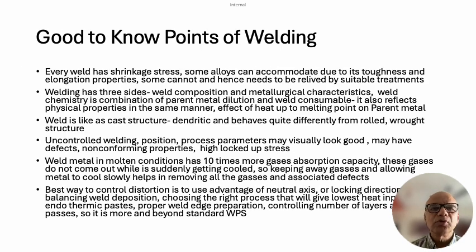Now there are a few good to know points in welding. Every weld has shrinkage stress. We cannot avoid it, because we are going up to melting point and then trying to solidify. In situ solidification in the weld edge preparation, and that too is not uniform all across. As we are progressing our weld, accordingly the weld is getting progressed and processed, so it takes certain time.